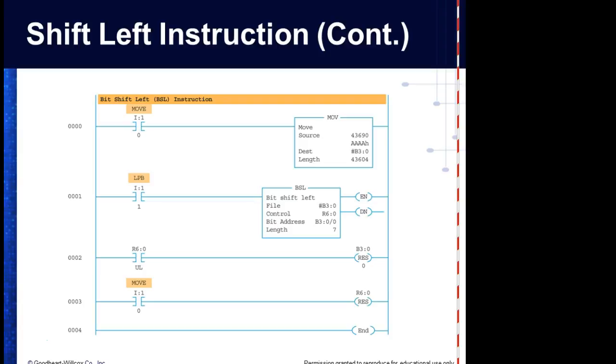Didn't I give you all that thing on addressing mode? So what does it say about that? What is the index register? It says S24. So S24, word 24 in the status file, is your index register. It's a 16-bit register that I can load with anything.